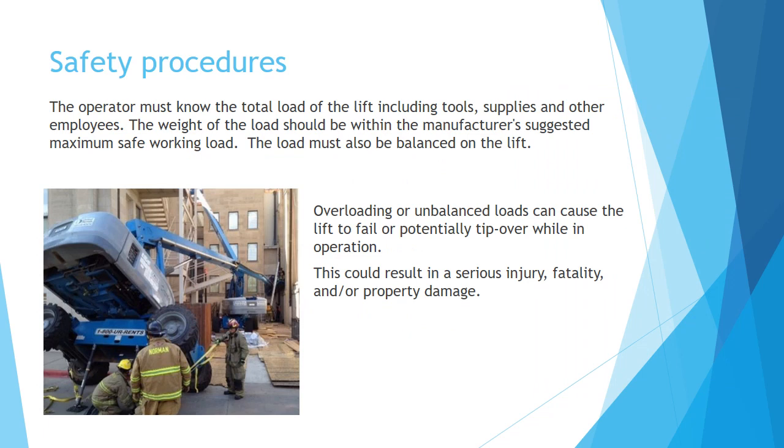The operator must know the total load of the lift, including tools, supplies, and other employees. The weight of the load should be within the manufacturer's suggested maximum safe working load. The load must also be balanced on the lift. Overloading or unbalanced loads can cause the lift to fail or potentially tip over while in operation. This could result in a serious injury, fatality, and/or property damage.